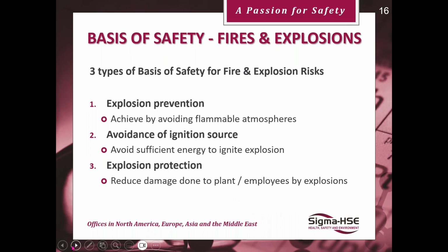Difficult in a lot of cases with dust in particular. With gases and vapors, you could work below the LEL or above the UEL and avoid the flammable atmosphere. You can use nitrogen inerting in these instances, but again, this system has to be robust and you have to make sure that it works correctly, with no guesswork involved.